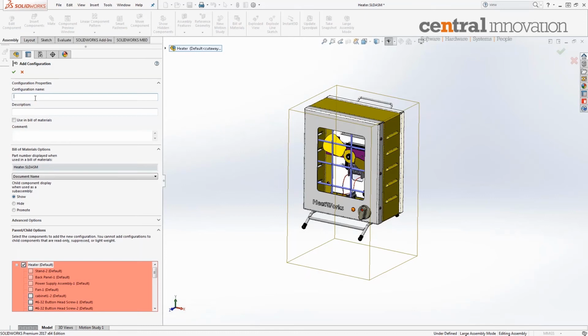You can do it directly from the assembly at the top level. Now, if you've got thousands of components, I probably wouldn't recommend doing it from the top level. You might want to break into some of the sub-assembly levels and do it from there. But you certainly have the ability to add simplified configs in bulk from the assembly level.